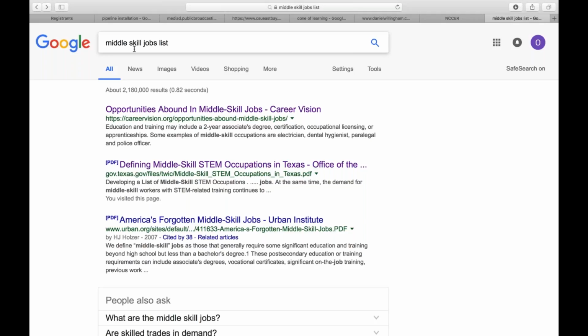One section is going to be the skill training. If I have someone that is a scaffold builder, they need to know how to build a scaffold. And the second part of that is they need to be hazard awareness trained on the risks associated with building a scaffold and where they're going to build it. Are they building it inside of an above ground storage tank? Hanging off the side of a building or a bridge? Inside of a trench? Or on top of some ground conditions that may not be ideal? Secure, but not ideal.